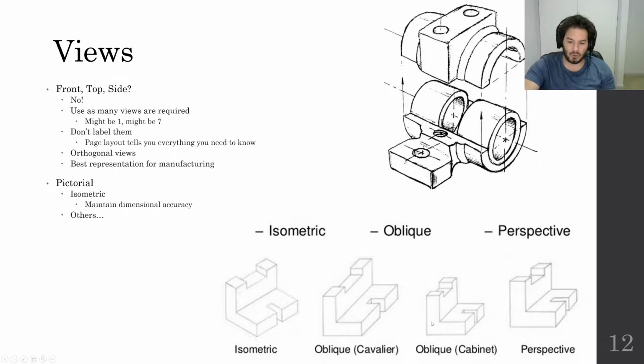Oblique views are interesting. What you do with an oblique view is you draw the front face perfect, square, as though you were directly facing it, and then you skew your other dimensions out. So if you make your other dimensions come out at a 45-degree angle and be half as long as normal, they kind of look roughly right, but then you lose all this accuracy on the sides. There is a use for it, and it's literally making cabinets. It's furniture making. So often with furniture making, your front face is really important, and you want to make a really, really good view of that. And then the rest of it's like, and then the table continues, or the cabinet continues, and then it stops, and it's plain. So if you're making furniture, go nuts with an oblique view. If you're an architect, go nuts on perspective. If you're an engineer, use an isometric view.